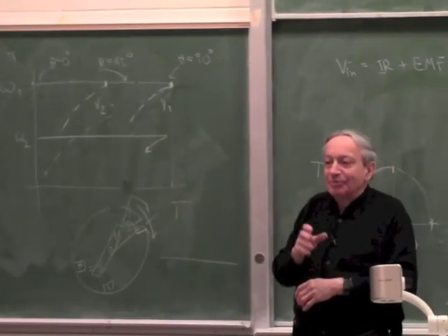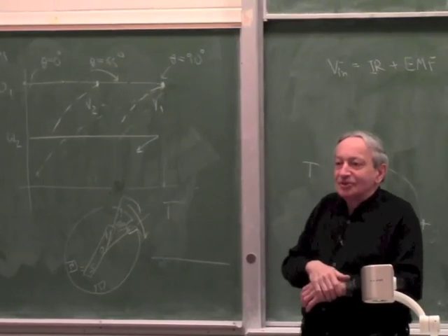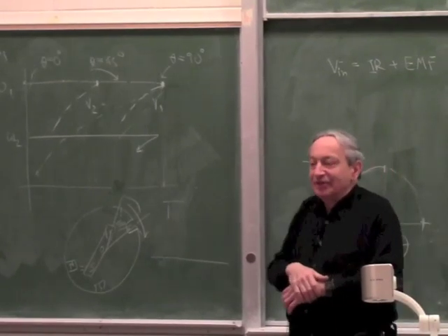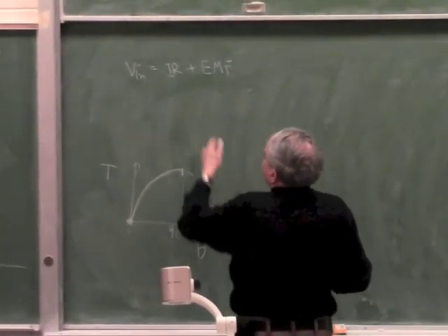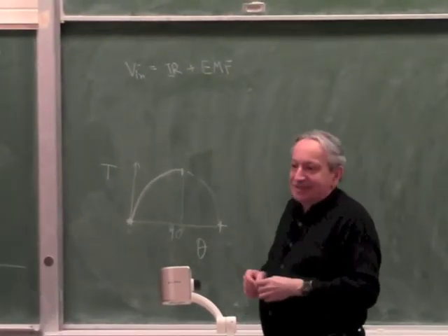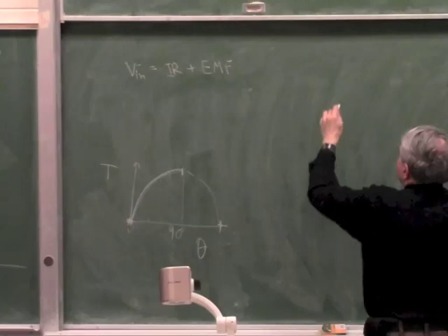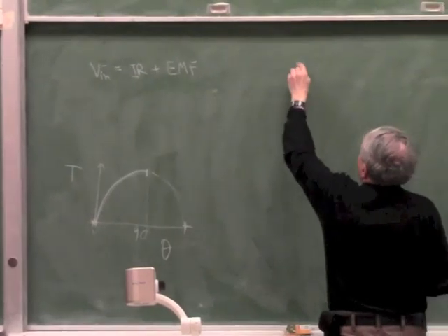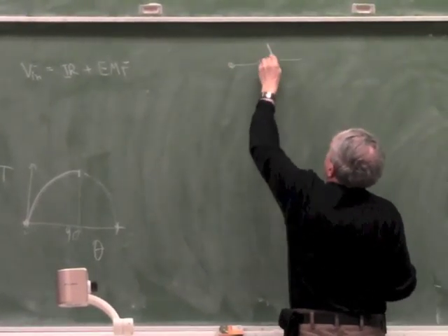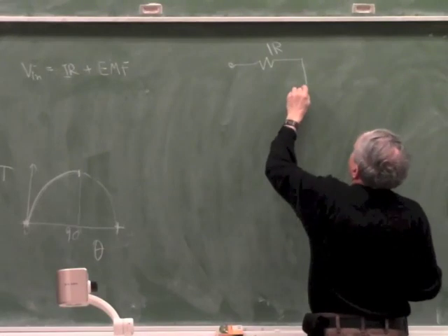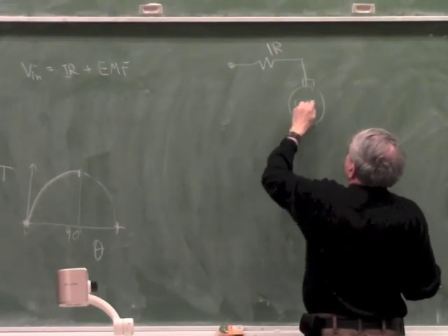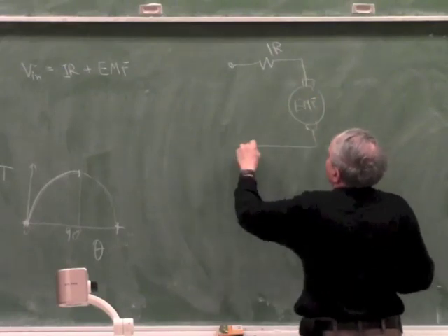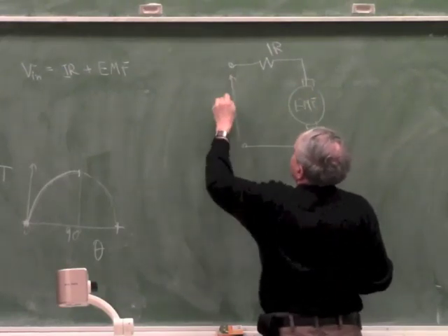In AC motors, it's a bit more complicated because there is also an inductive component. So actually, the R in an AC motor is not only R, but it's actually Z. Because the way they draw the model, in a DC motor, we drew IR, and then we drew the back EMF created by the rotating rotor, and this had to be equal to V.